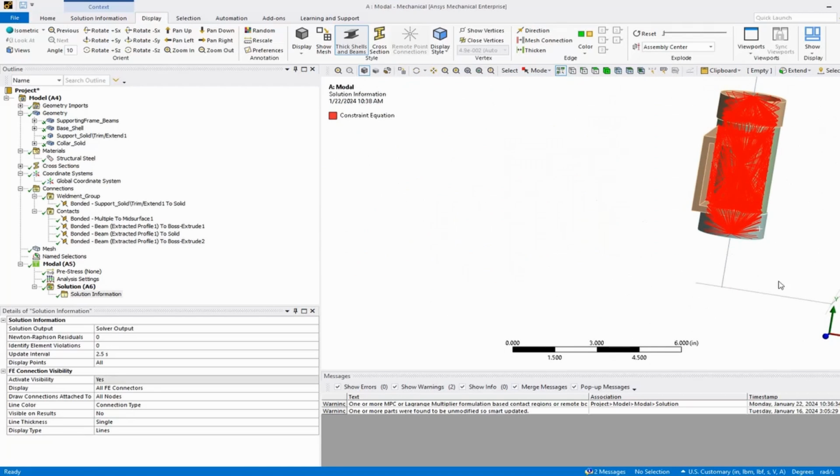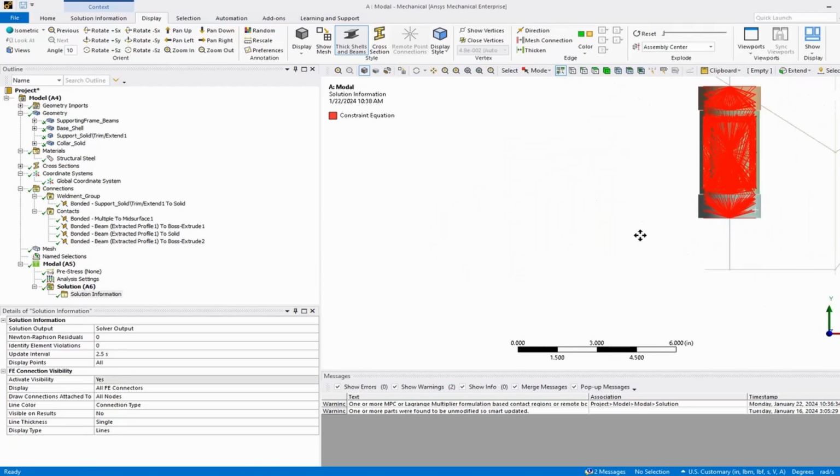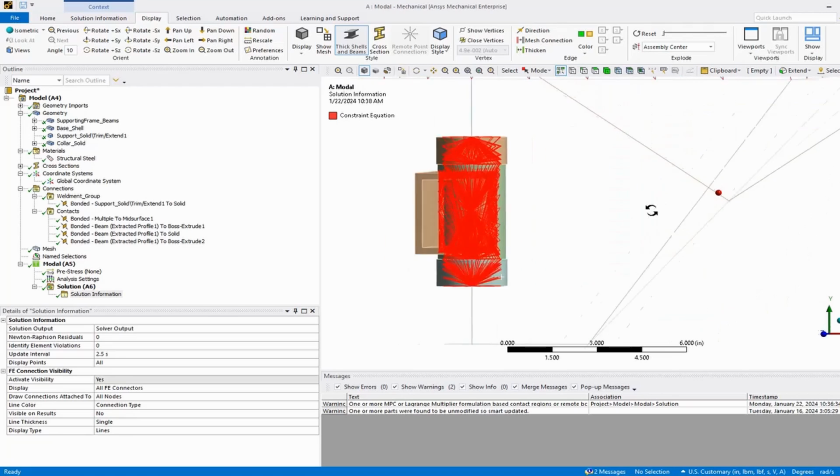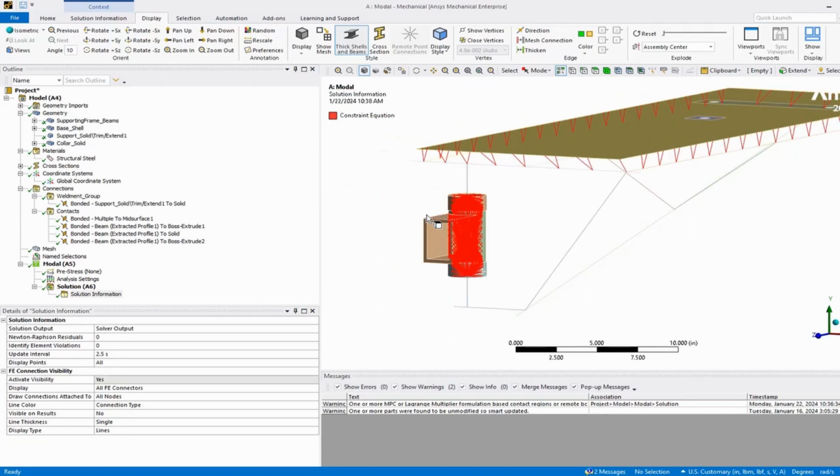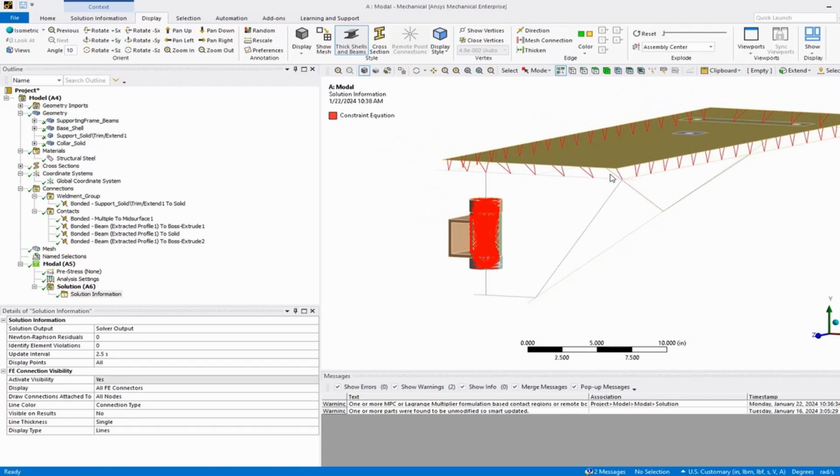And you can see here, that's why I like to use multi-point constraints, because I can go in here and see what nodes it grabs, because in a lot of cases you may not be able to tell with the program controlled constraints. So hope you learned something, and I'll see you next time.